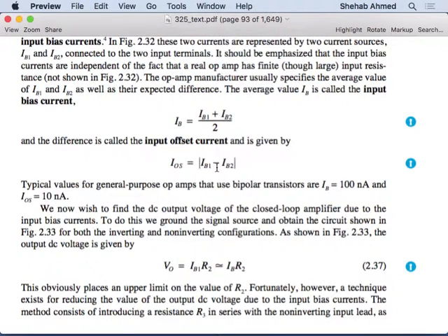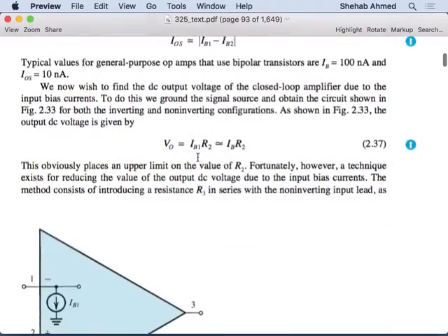If they are very similar, then what is the offset current? Much smaller than both of them, right? So if I'm able to come up with a circuit that is not affected by the bias current itself, but affected by the offset current, then it's nice. It's like not magnifying the offset voltage and sending through only the offset voltage, like we had before. So it's the same sort of mentality, same sort of issue.